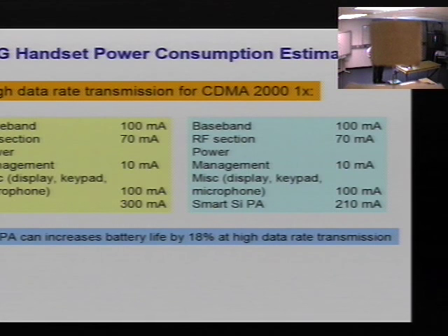When the CDMA 2000 1X standard was first adopted in '99, one of the selling points was that compared to IS-95, it doesn't need to change anything in the analog portion, except for some filter tuning to bump up the signal to noise ratio. All the amplifiers, mixers, just everything stays the same, and that's what makes it cheaper.